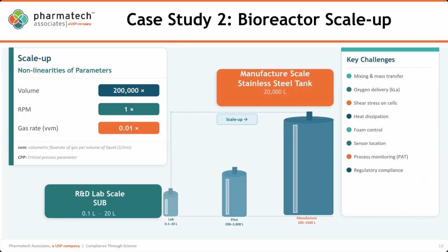Quality by design is not DOE, is not just PAT, is not just showing the data. It is the understanding of the correlation of the CMA, CPP, and CQA. Why did that happen? If you change your RPM, the impurity went up. Why? That's why FDA is expecting companies to explain and demonstrate that they understand the risk, the process, and the material. All of these mechanistic models go to the core understanding of the correlation of different properties, parameters, the reactions and the kinetics, and all of that could also help with the review time.